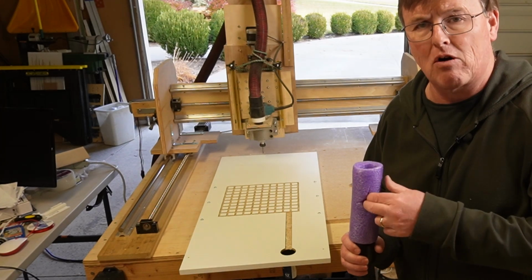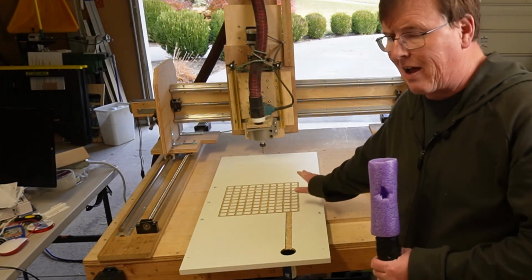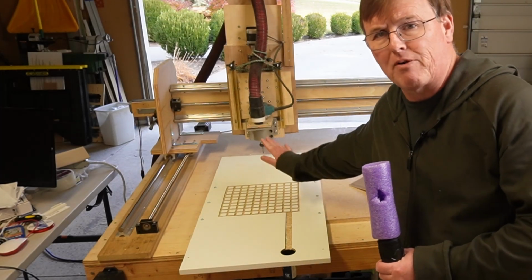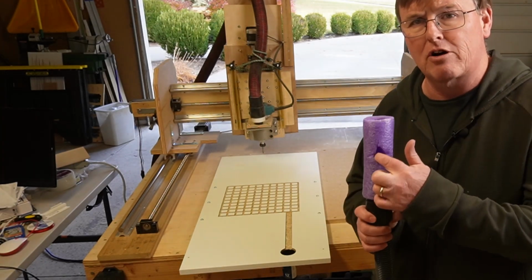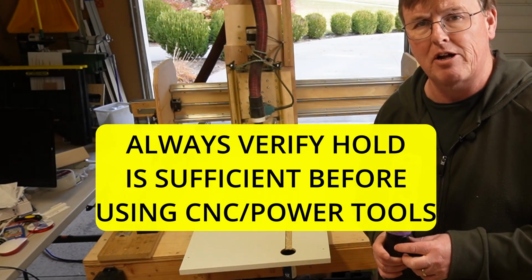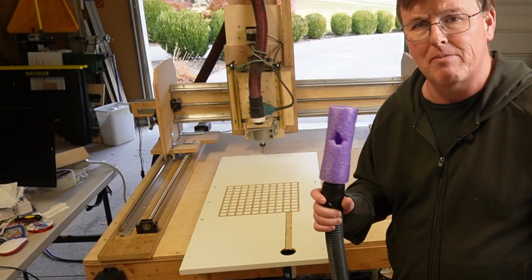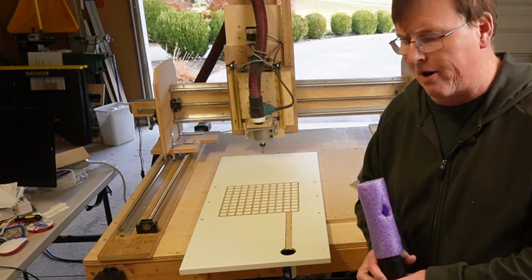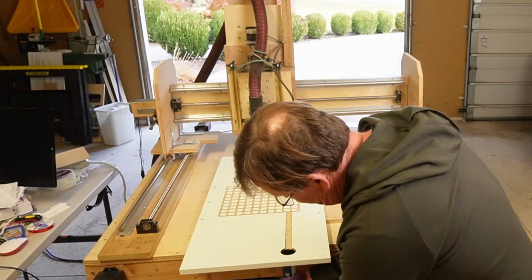And even with that air hole, which of course is going to diminish your vacuum a little bit, it will still have plenty of suction to pull down a board flat for the purposes of V-carving. So I strongly urge you to do that. Otherwise you could overheat your vacuum, and this will help alleviate that. Still monitor your vacuum temperature, otherwise you could potentially burn out the motor. And so we're going to go ahead and slip this on here like so.